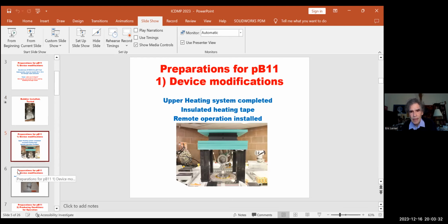So we've had to make some modifications to the machine to accommodate the need for heating it continuously while it's on. So we have this upper vacuum chamber for the E-beam. So we had to install heating tape and insulation on top of it so that it could be totally electrically isolated. Because when the machine operates, this top plate, of course, goes to 40 kilovolts.